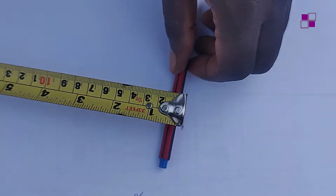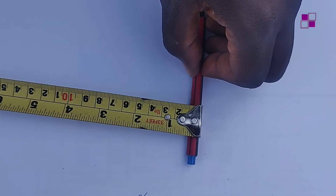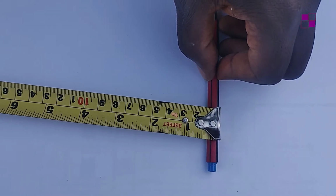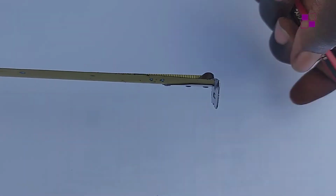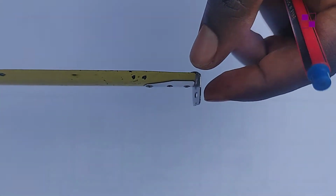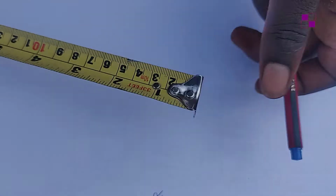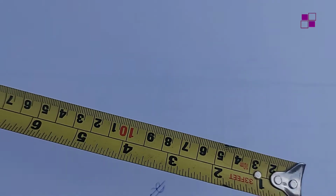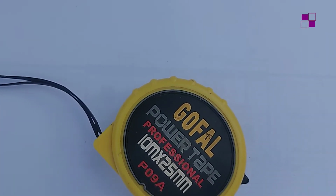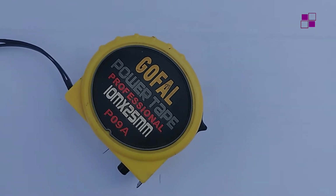Now, if I'm taking measurement out of a particular part of a building, that means I have to hook the tape outside here. So this metal will project outside a bit. Projecting outside is covering for the thickness of the tape that will form part of the reading as you start. So another important thing that I need to tell you before we go into reading: I know a lot of us just want to get straight to reading the tape immediately, but you need to understand some parts of the tape before you proceed into action.